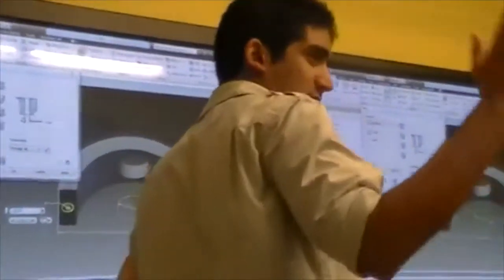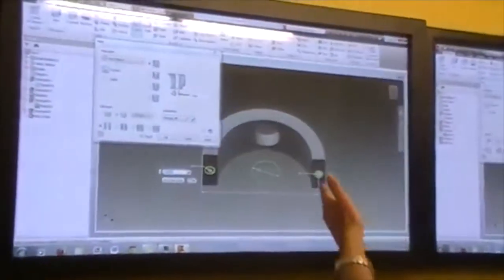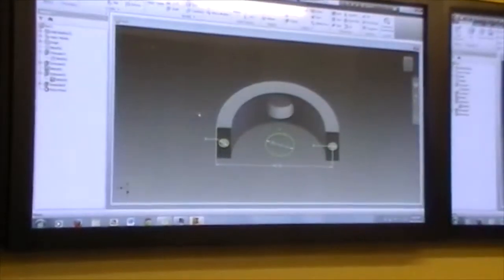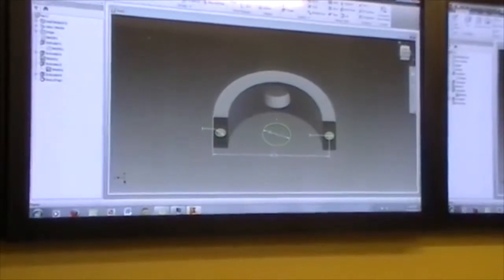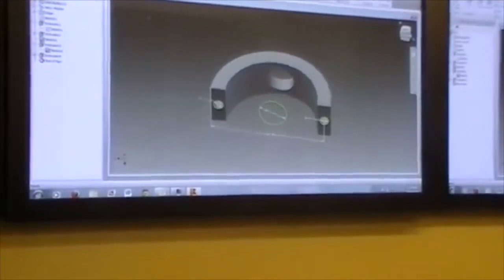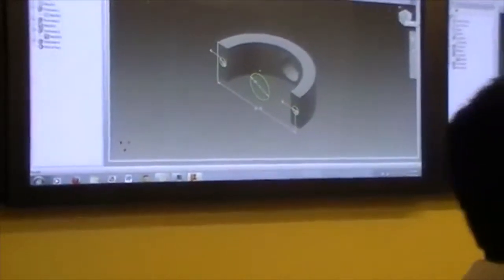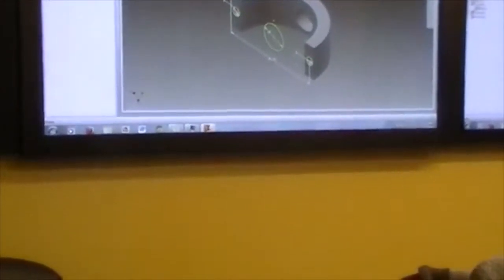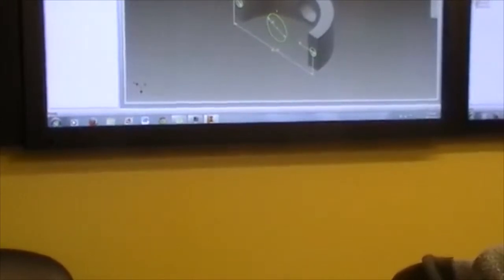We're just drilling simple circles, so you can use a cut, but I do suggest that you explore the hole feature if you're trying to actually use a fastener. So we'll just cancel this, and now you've got something that looks actually pretty useful, right? This is what you were kind of looking for. It's got a band, a hole, and then 2 pins to fasten with.